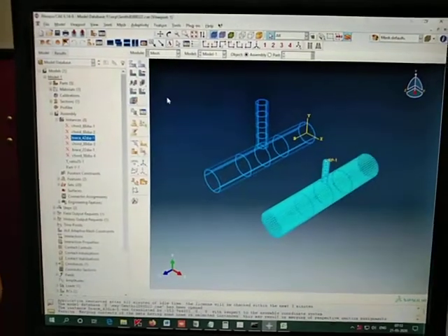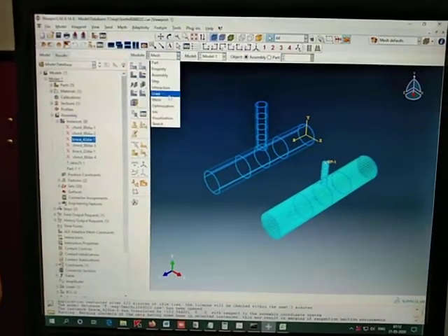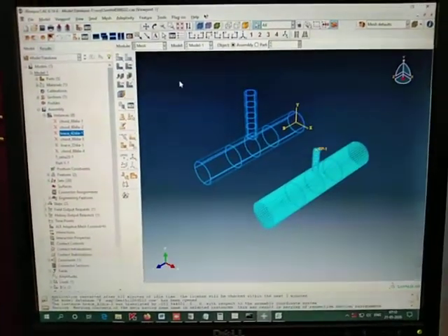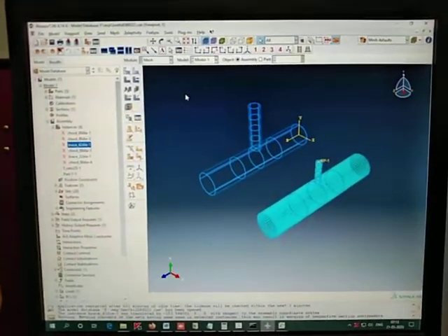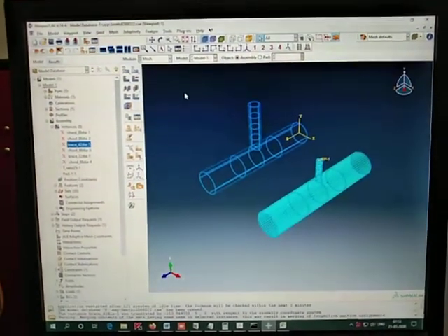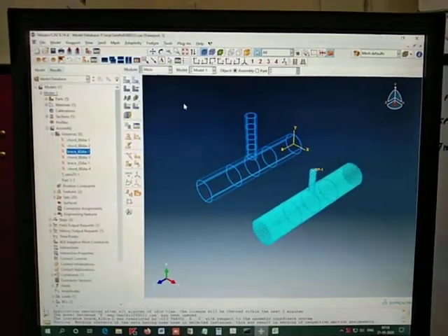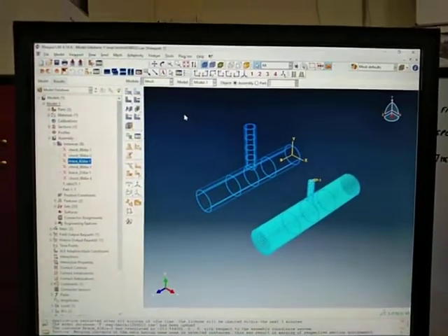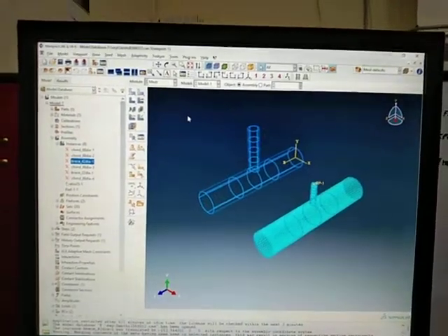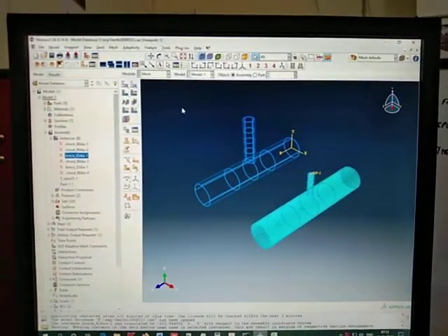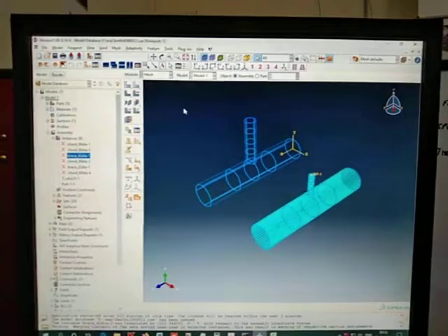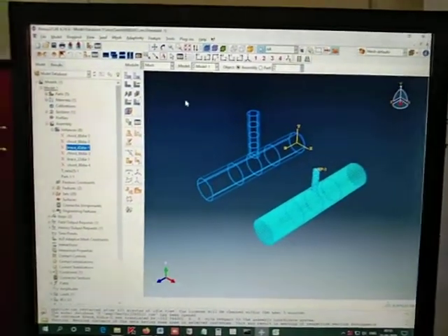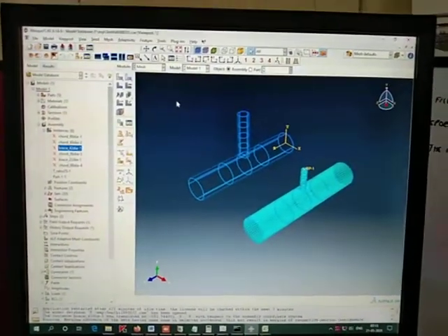Then at the later stage, for the mesh size of solid elements, it is better to use solid brick elements of 8 nodes for approximate analysis. To have a much more critical analysis, it is better to use 20 noded elements. While the 8 noded elements are most suitable for these bending problems, the stresses will be more approximate, and hourglassing effects are there. To avoid that, we will go for C3D8R, that is the reduced integration.